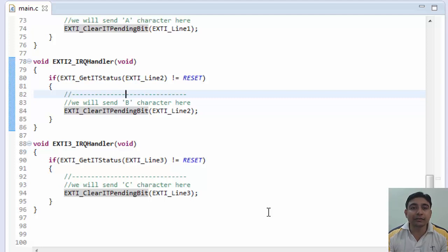So let's start configuring the USART3. First, we need to put the transmit pin PD8 in alternate function mode. Till now we have seen many times where we configured pins in either input or output mode, but this time we are using a microcontroller pin for a USART peripheral. So here we have to use alternate function mode. Let's do it one by one.